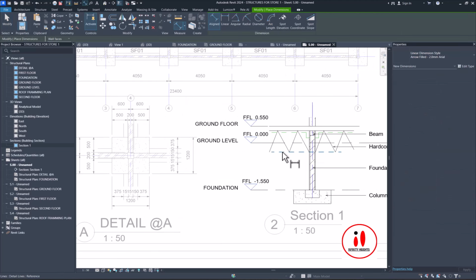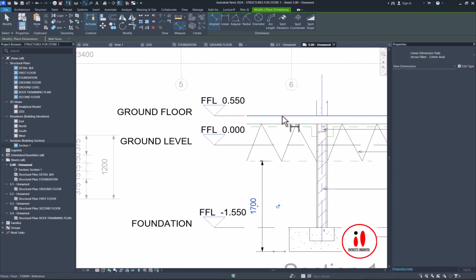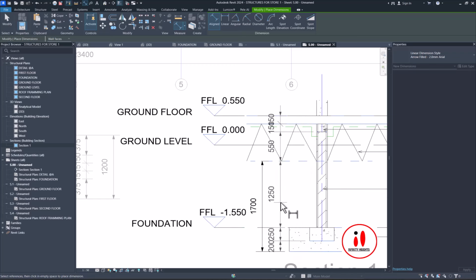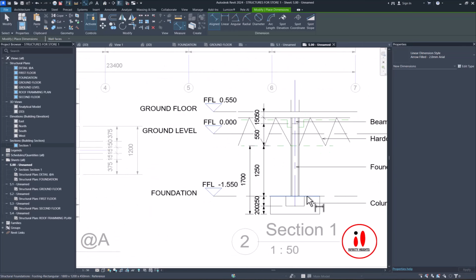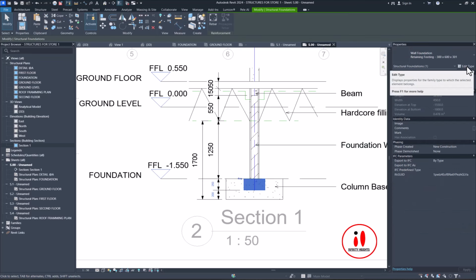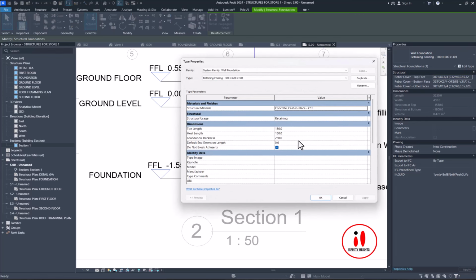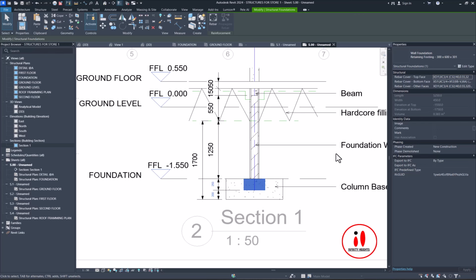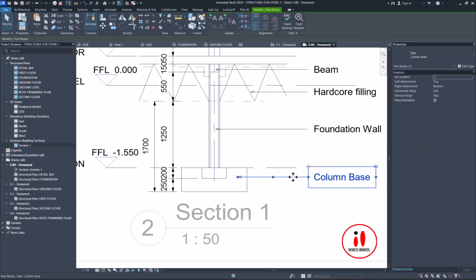Of the depth of the foundation. So after the excavation, they should dig 1.7. That will be the depth that they should go. Then you can also give them information about the beam from here to here, the size of the strip. Is it standard? This standard, you have to do it 200 by 450. Yes, so the depth has to be 200 and this one has to be 450.